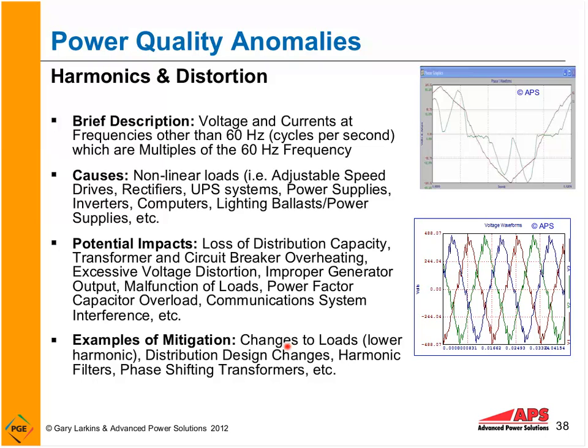So here we can see this is current flow from a 6-pulse adjustable speed drive. Now, if that was a standard motor, as the voltage went up here, which is this waveform right here, the current would go up and drop down in a linear fashion. But this is what's called a nonlinear load, which draws current at frequencies other than 60 hertz and causes harmonics.